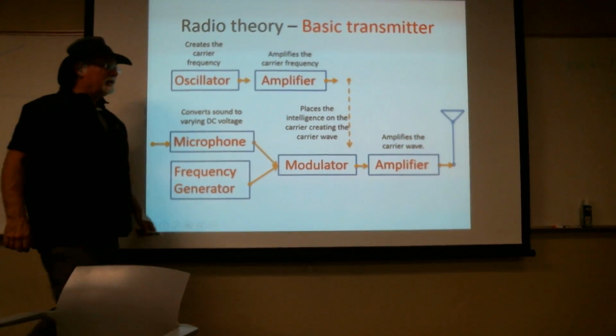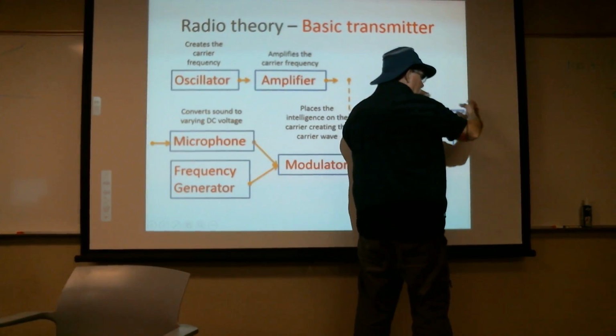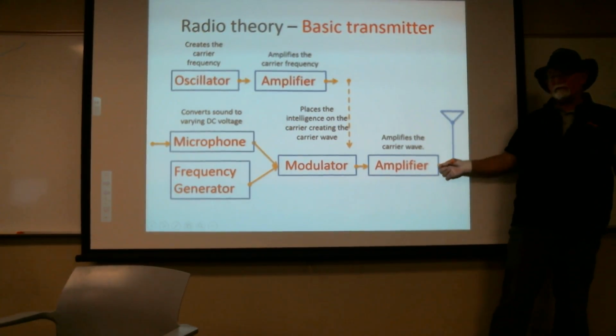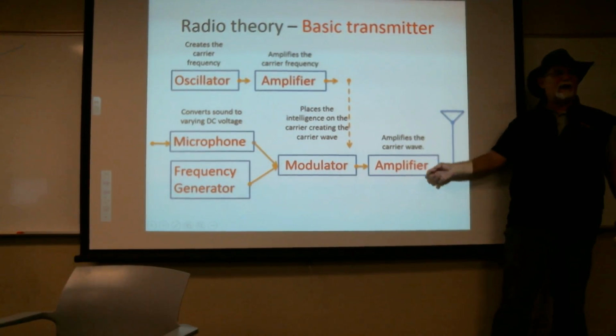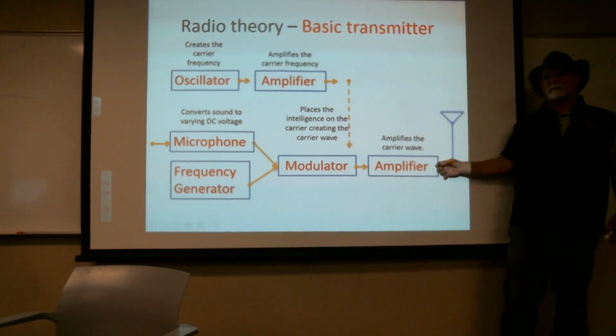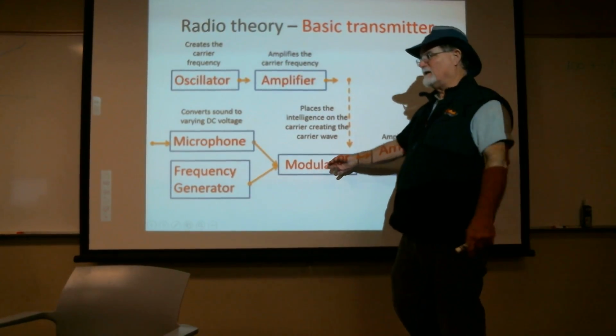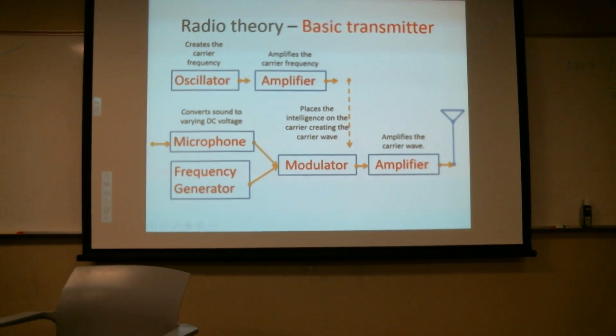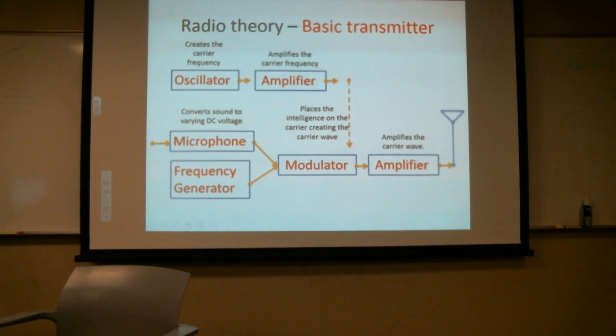If I don't have an antenna that's creating this big magnetic pulse, what I'm now going to have is a fair amount of voltage and current here going nowhere. So it might try to go somewhere inside this output amp, which would be bad for it. Might even break things further back up the line. So never, ever, ever, receive, no problem. Transmit, never, ever, ever transmit without an antenna attached. Particularly without the appropriate antenna attached.